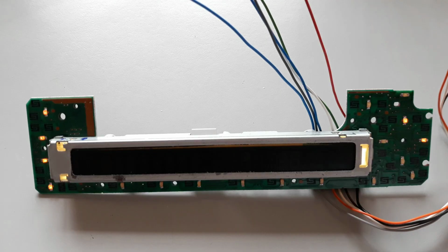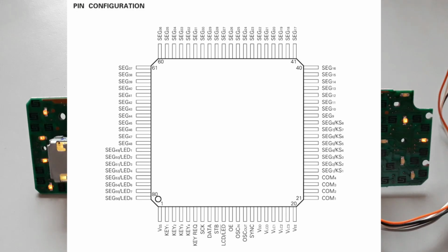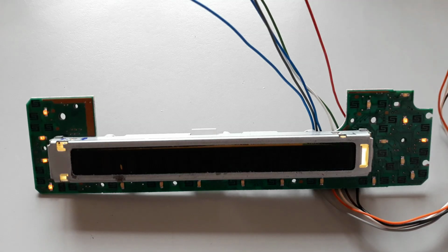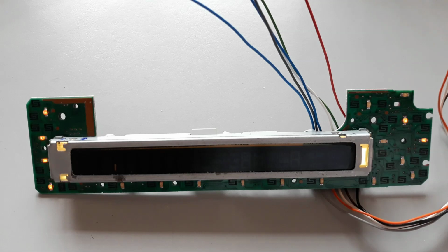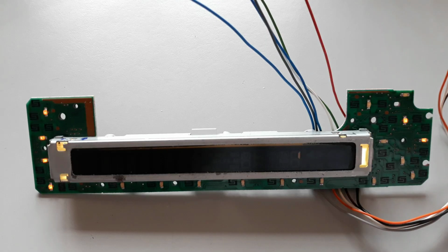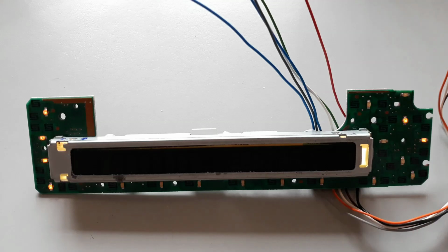However, if we decide to use the pins that provide the LED output function, the available number of LCD segments is reduced to 192. That is because we lose 4 groups of 8 LED ports, one group for each COM line. In this project, we will use the maximum segment configuration. This is also the default configuration after the driver is initialized, even though the display we are using only has active segments up to 3/4 position.